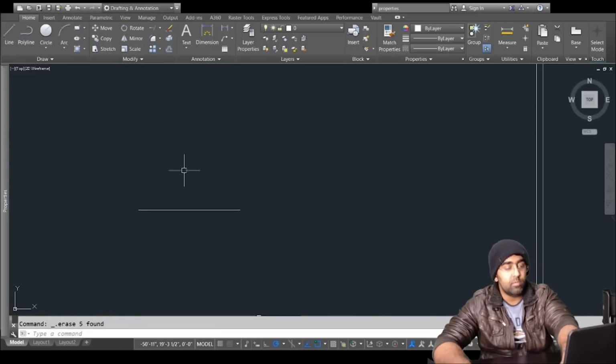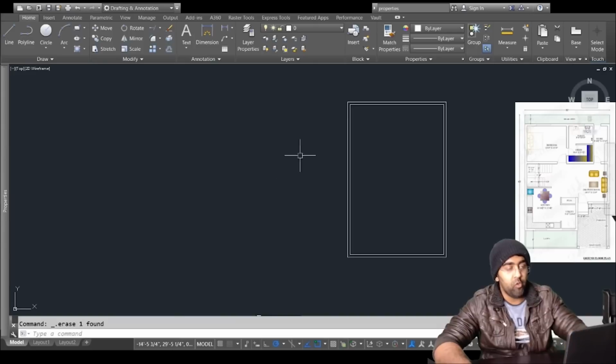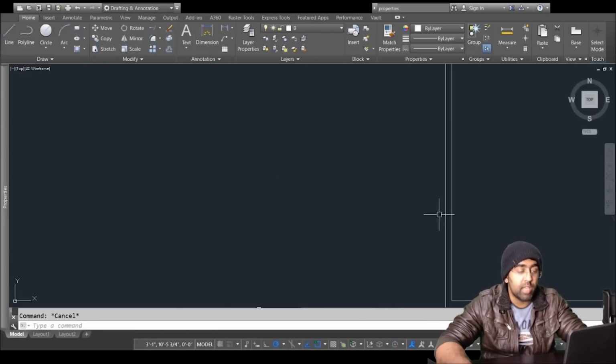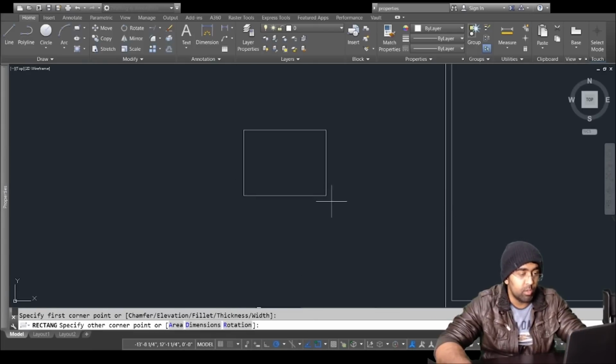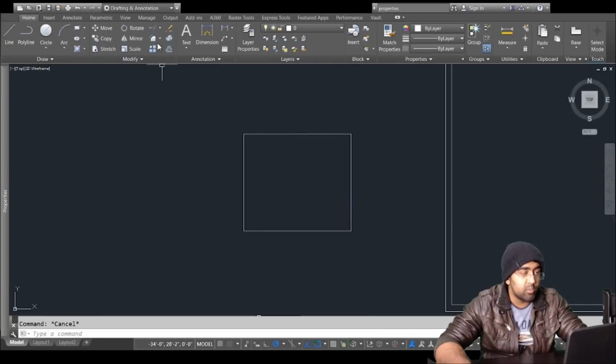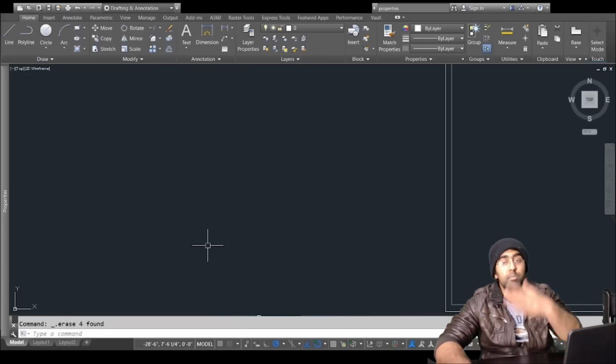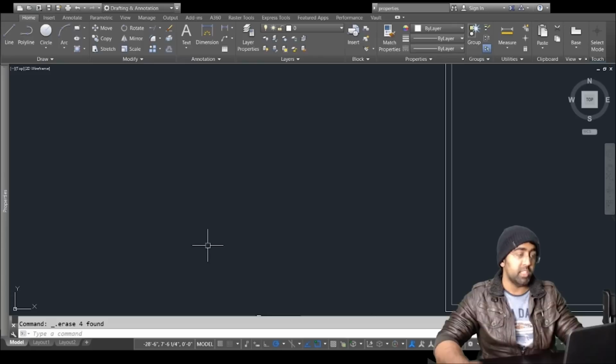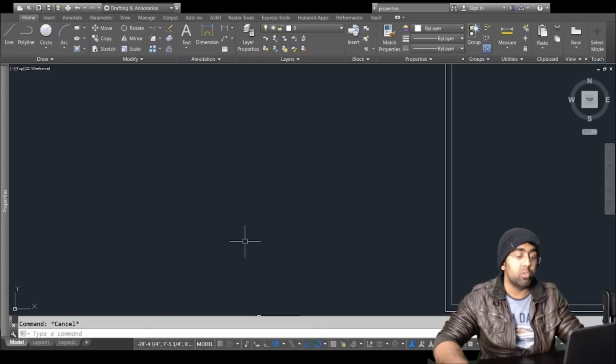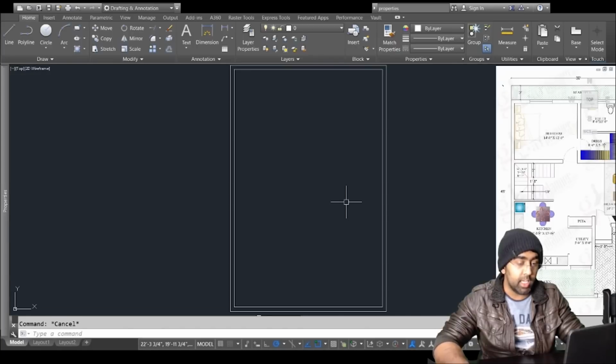That is why I have to explode that. So if I want to explode this rectangle, I have to use this explode command, and I'll select this rectangle and press spacebar. Now these are all separate objects, no more rectangle. Alright, so it's still a rectangle, but it's not combined. We can join them as well.